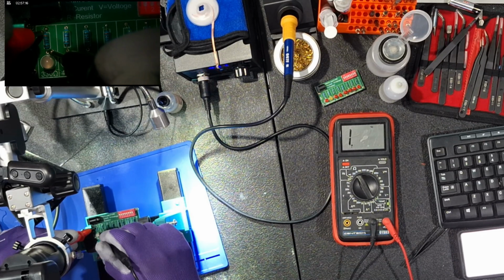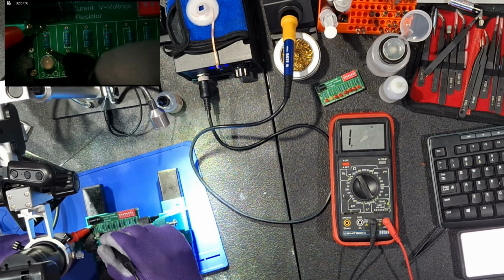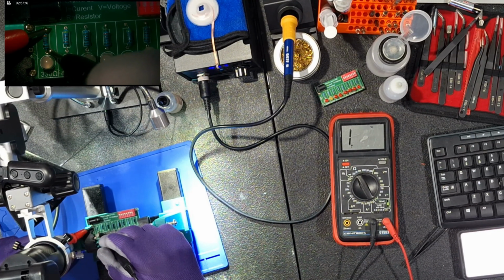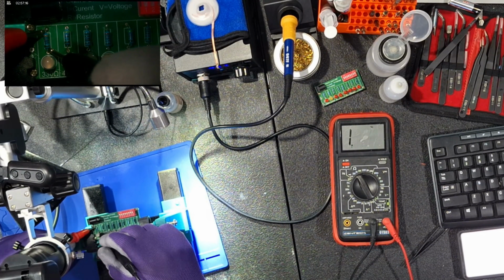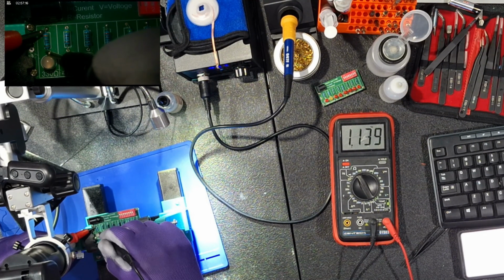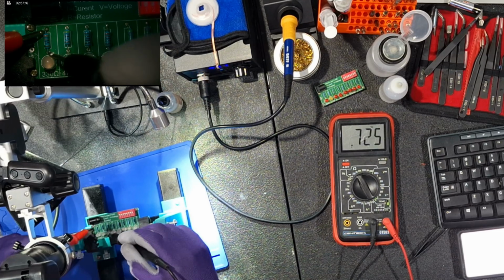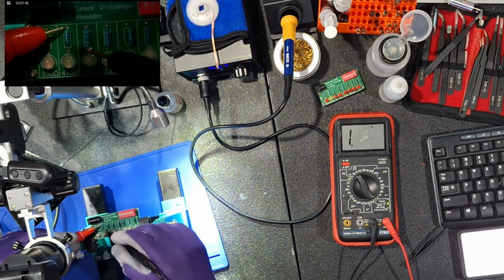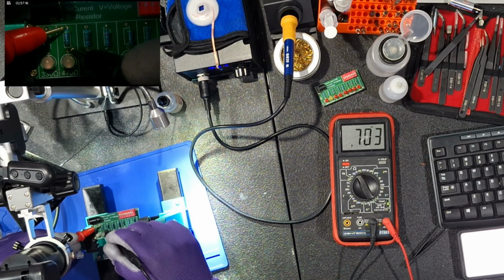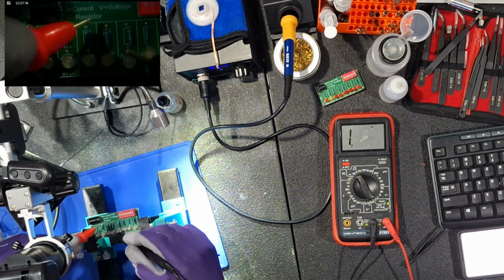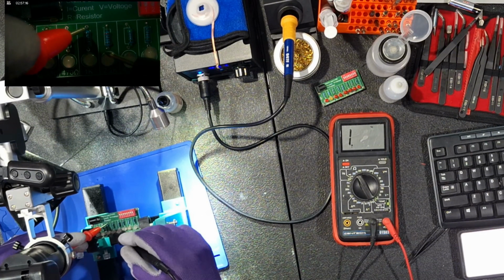So for resistors like 10 ohms, 100, 300 ohms, 330, and so on, you get a reading. But when you go above 1000 ohms, up to 2000 ohms, 20,000, 200,000, you won't get a reading. This was confusing me, because I was asking why some resistors read and others don't. But later on, I figured out that you have to turn the dial each time based on the value that you are testing.